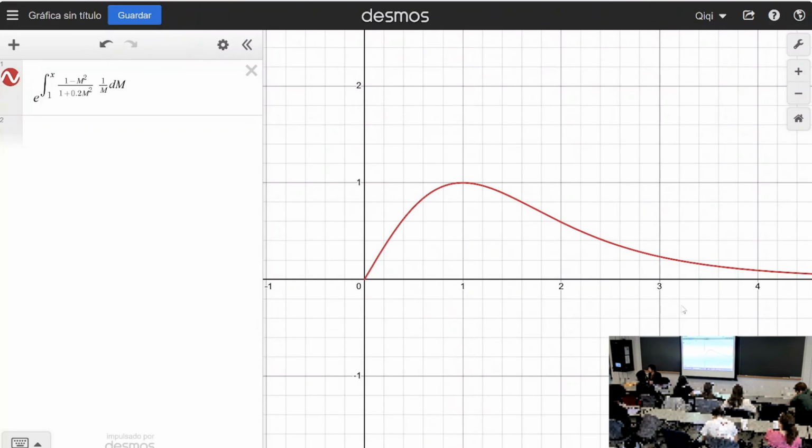How does it depend on the Mach number? At a small Mach number, we get a linear relationship. As Mach number increases, the mass flow per area increases linearly. But that relation starts to become almost flat at Mach equal to 1. At Mach equal to 1, I get the maximum possible mass flow per area, rho u. And beyond Mach 1, I get a decrease. Which means if we draw a convergent divergent nozzle, and if the whole process is isentropic, with no shock waves,